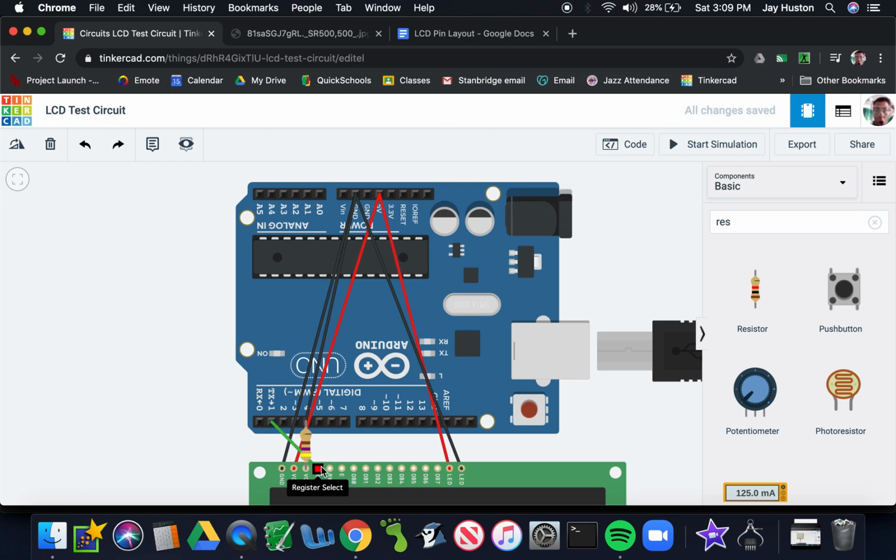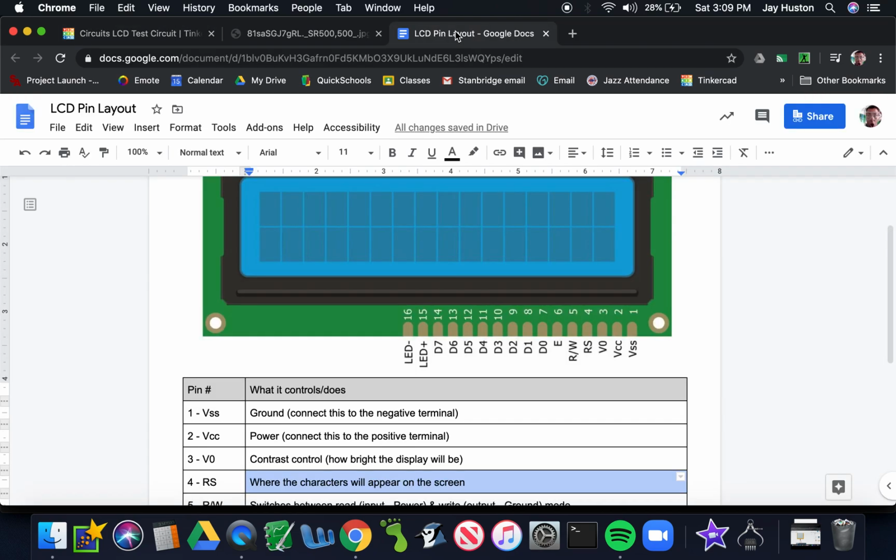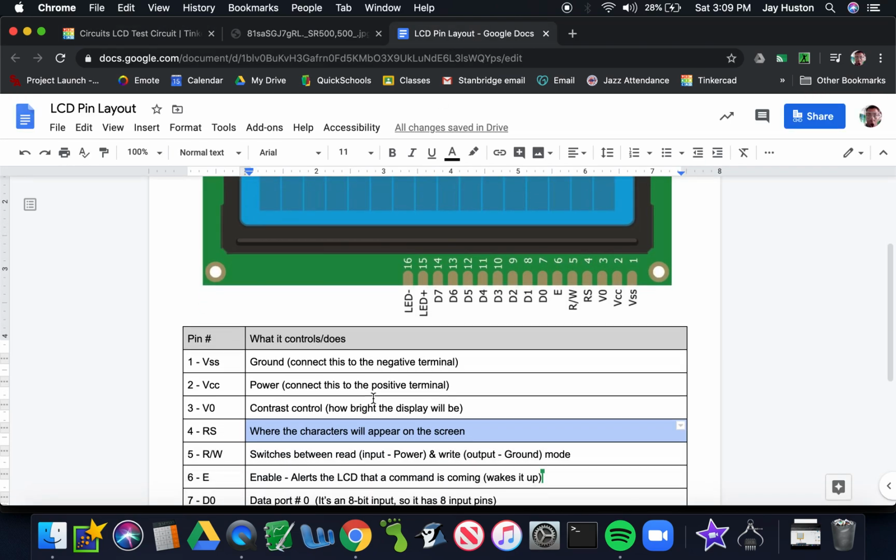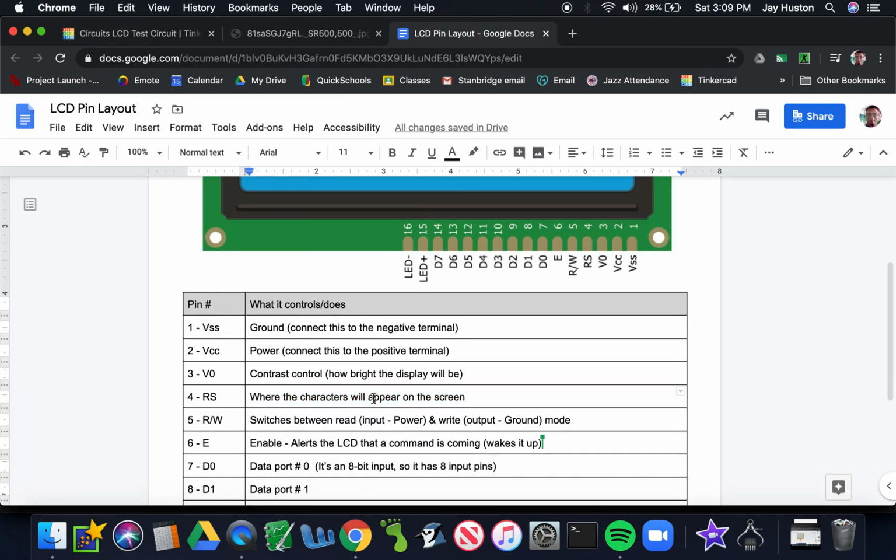This right here, the register select, says where we want to print it, and I'll code it so that the pin 1, the Arduino knows to send that information out pin 1. Okay, so RS is attached to pin 1. Gotcha. And you should be following along, so you should be pausing the video, wiring your own, starting the video back up.